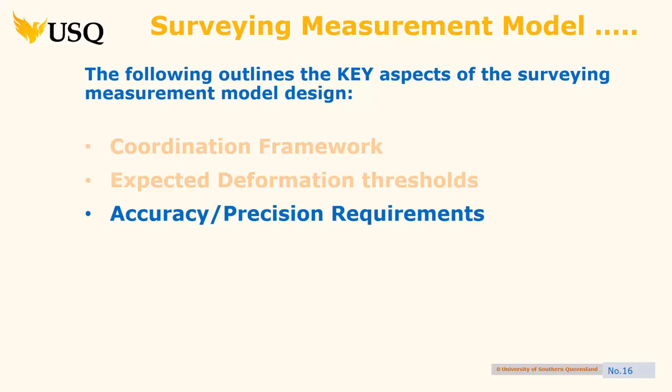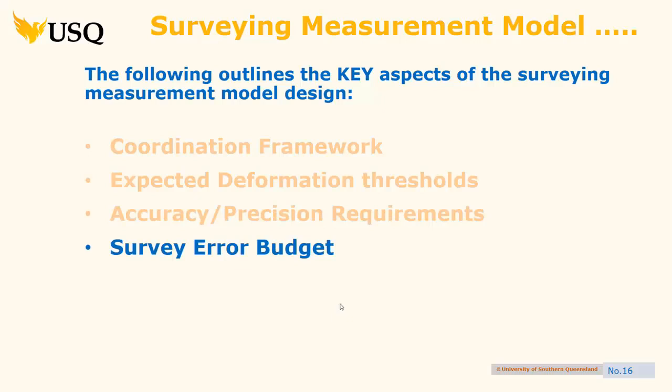Because particularly when you prefab, anyone who's built a garden shed at home even knows that the thing you measure all the time is the diagonals, because it doesn't like being out of square. It doesn't fit, right? So that's the types of things.